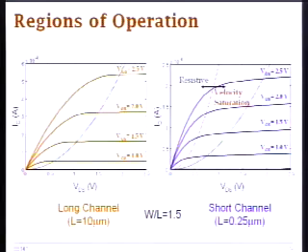So now, in order to analyze this device, it is of interest to develop some really simple analytical models, so that we can do some quick calculations. And the point in developing these models is really to understand which parameters are the most important, and develop models around those parameters, and also fit the curves in certain regions that are important for us to do the calculation, because including all the physical parameters is really getting out of hand. That's what you're going to do in SPICE. Plus, as you will see in your labs, when you do layout, you will have other effects that you don't account for. You have lots of parasitics and resistances, capacitances from wires and things that you don't include in these simple transistor models, and we'll get back to that later in the class.